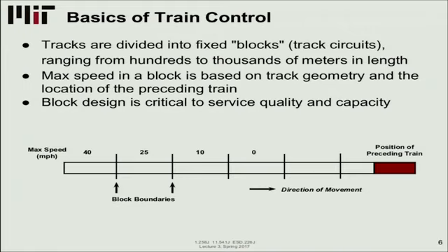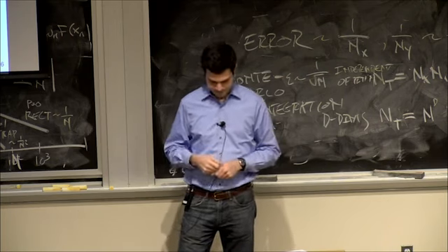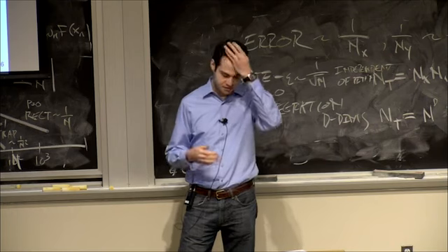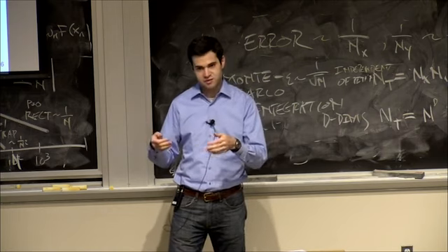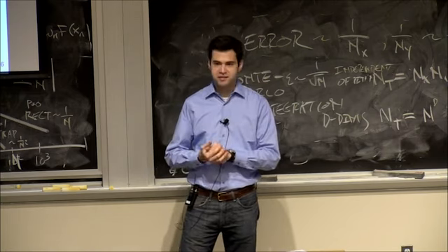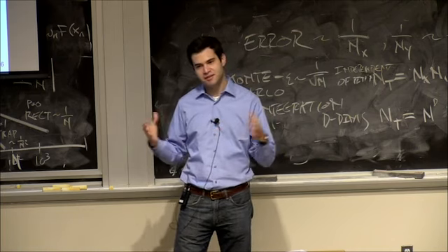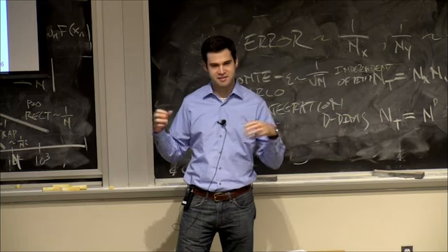It does that by setting the speed limit on the segment two segments upstream to 0. So if a train were to enter that segment, it would be braked automatically. And then the speed limit gets increased as you go farther upstream. So a train can move along the track, but if it gets too close to the piece of track being occupied, it'll have to slow down or brake. Have you been on a train here or elsewhere where you're braked all of a sudden in the middle of the track between stations? Yeah, and then normally you hear the brakes going off, and then it starts again.